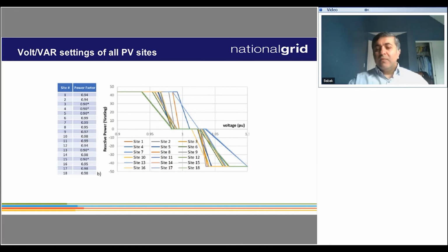So where am I going with this? As you add more and more distributed energy resources to the grid, things change. Things change in terms of the impact on the existing volt-var curves. So the slope of the curve is going to change as you add more DER to the grid with reactive power capability. Now, there is no guarantee that all these DERs are going to be on all the time. One can be off tomorrow for maintenance reasons.